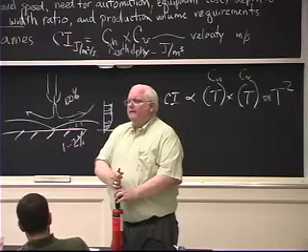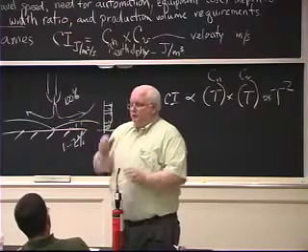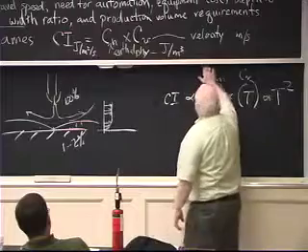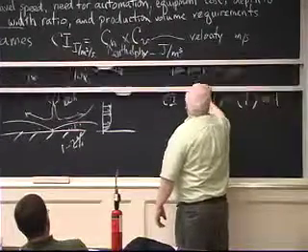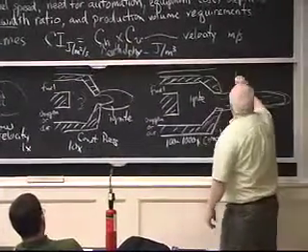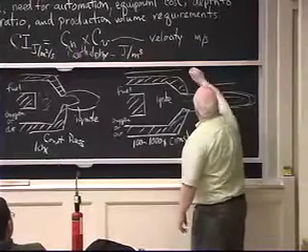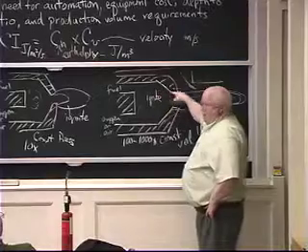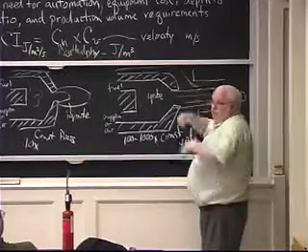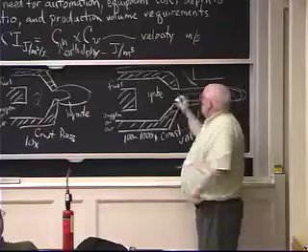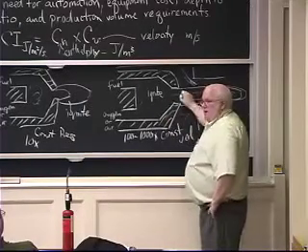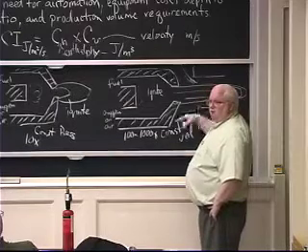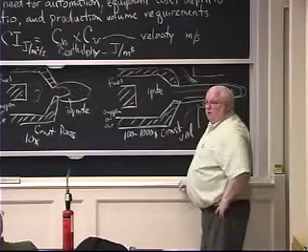What's the principle of an afterburner then? An afterburner is just a jet burner. You add an afterburner after a jet burner, essentially as a second stage where you inject fuel into this. You have to have some air come in here too, because if you just inject fuel and there's no leftover air from this, then you need some excess air and fuel. But this is your ignition source, and it's coming out at high speed. Now you're essentially putting a jet burner behind a jet burner, getting that extra boost and burning fuel like mad.